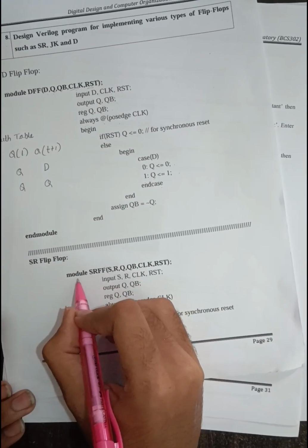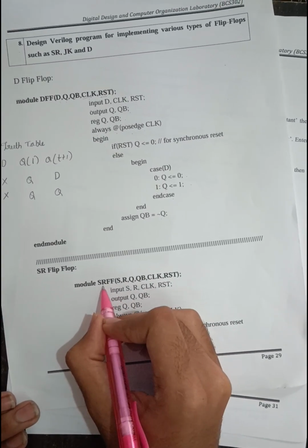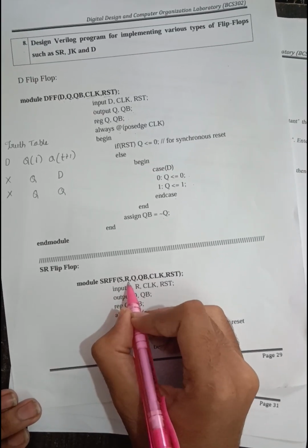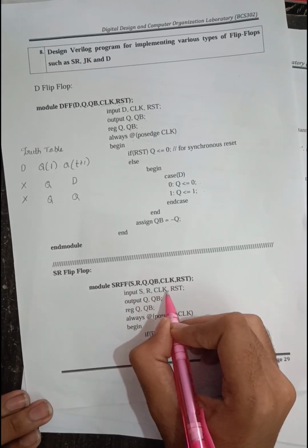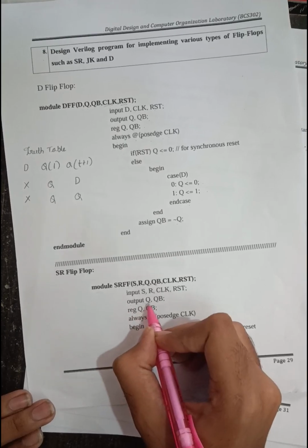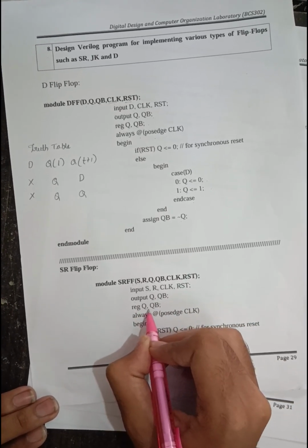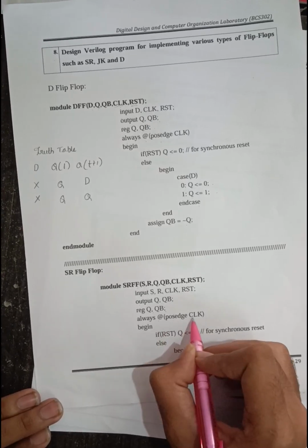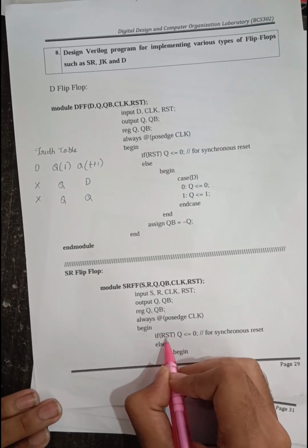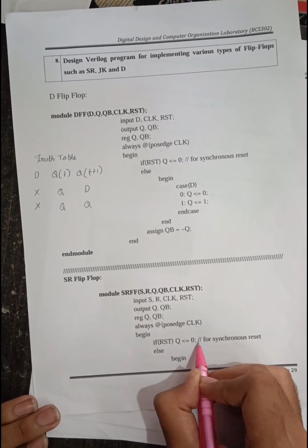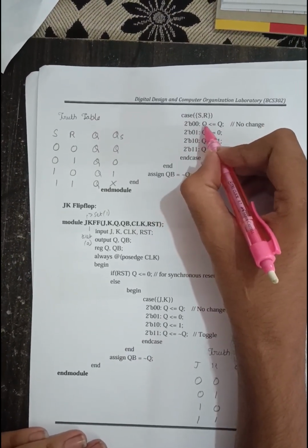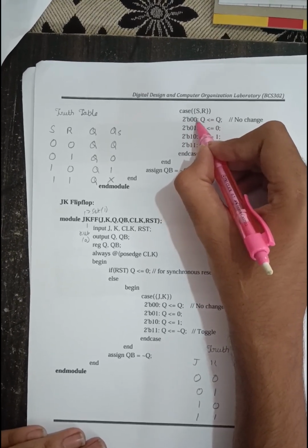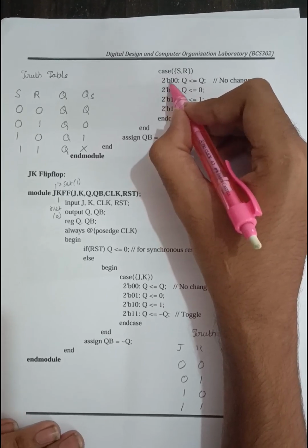SR flip-flop. Assign a module SRFF, set reset flip-flop. It consists of S, R, Q, QB, clock and reset. It consists of inputs S, R, clock and RST, and outputs Q and QB, registered with Q and QB, and always consists of clock. It begins with if RST, reset of Q less than or equal to 0, or else begin with case of S, R. 2'b of 0. Now assign values like decimal values 00, 01, 10 and 11. 2'b of 00,